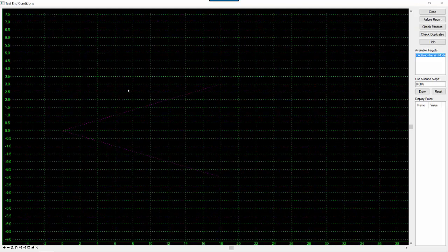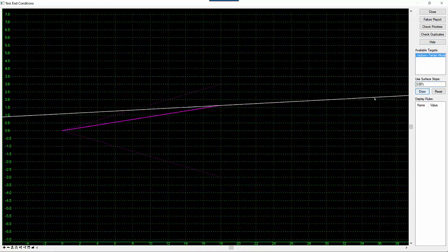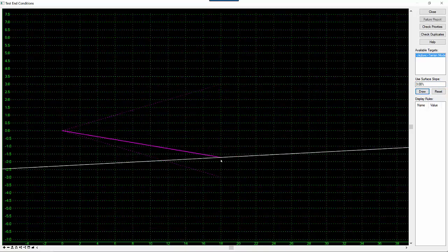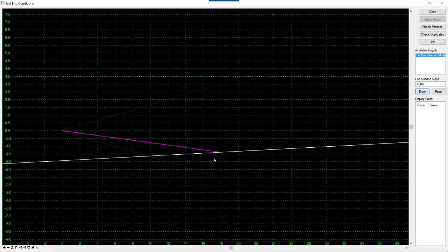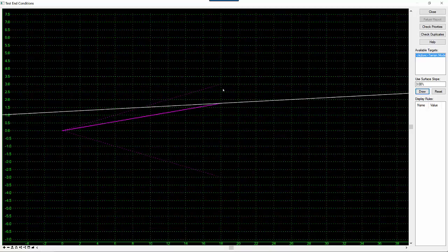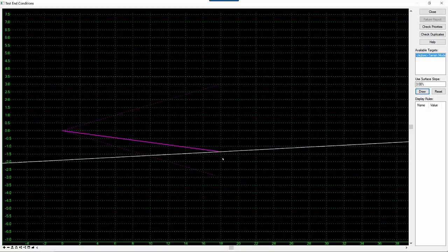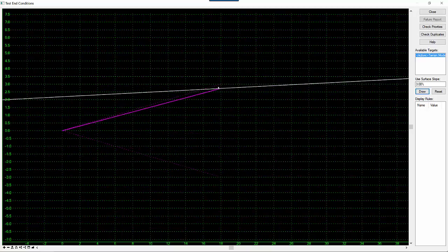And there you can see our end conditions. I'm going to put in my active terrain model. Again, I like to set this up something other than 0. I'm going to click draw. And now you can see between those 2 points, positive 3 feet and negative 3 feet vertically, 18 feet away, we have a variable slope solution.